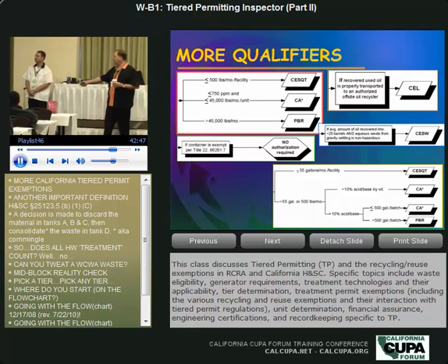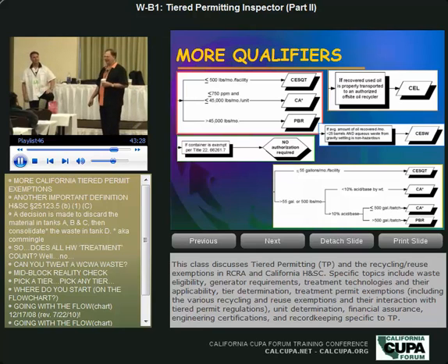Well, yeah, see, it has to meet all those requirements. No pourable liquid. Well, it's going to squirt all over the place. No, because if you're crushing a drum with liquid in it, never mind you're going to get squirted, that drum with liquid in it doesn't meet the 66-261.7 exemption. Therefore, it's not eligible for tiered permitting at all. That drum has to be empty before they crush it. It has to meet the California empty, Mike. California empty, not that EPA one-inch easy-going nonsense. RCRA empty. Yeah, none of that stuff.